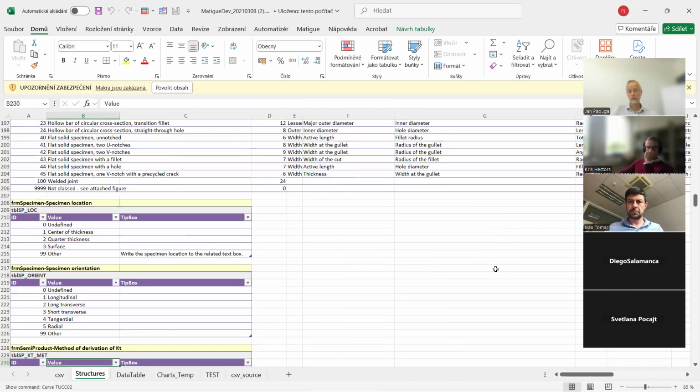Yeah, in our case, in the Fabus, we have a semi-product rod of 35 millimeter diameter, and we know that up to a depth of 15 millimeters or maybe 12 millimeters, it has significantly different hardness and also fatigue response than the central core section.